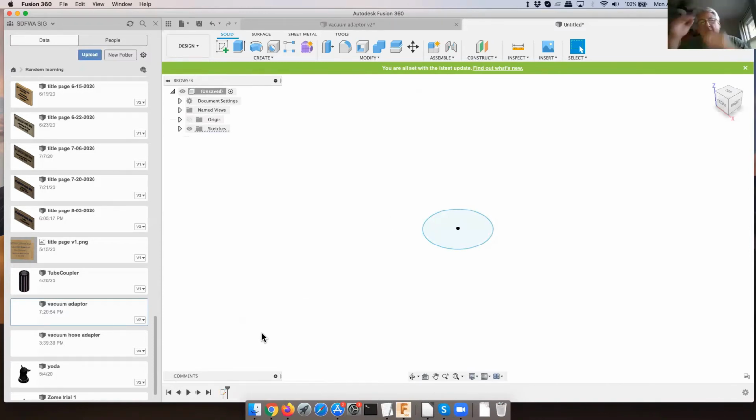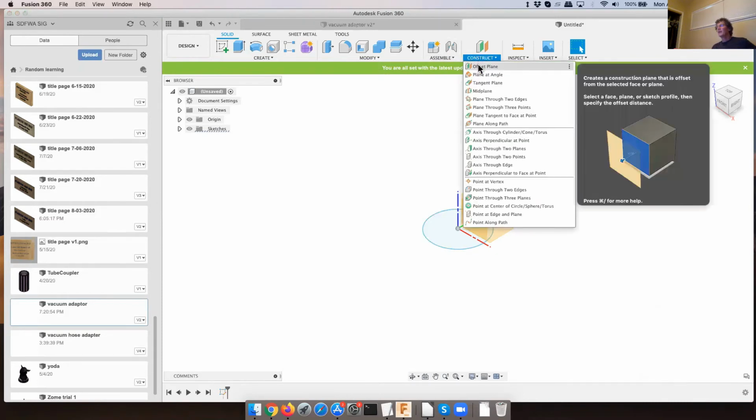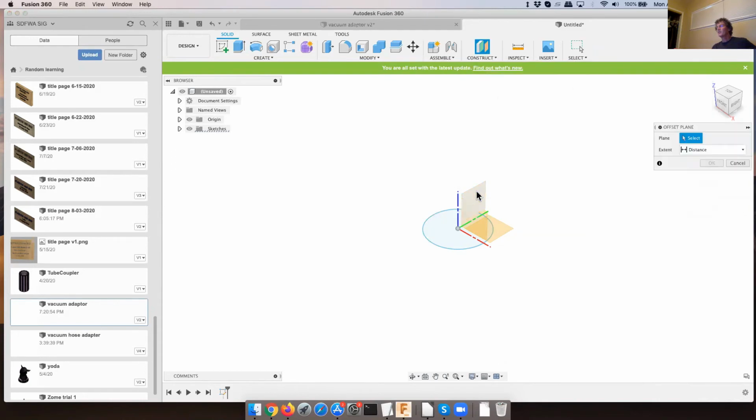I guess it's kind of like a chicken and egg syndrome as far as what is the first thing that you reference off of, because everything else would... Yeah, for me, it's usually, what's the easiest point for me to use as my origin? What are the logical XY planes, etc. And I go from there. So creating extra construction planes is usually quite useful.